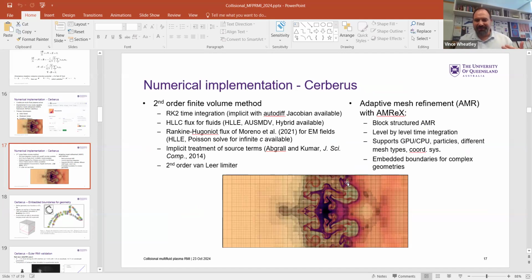So we use adaptive mesh refinement to greatly refine the cells around the solid boundary. But then we slightly unrefine them if those cells would be too small when we cut them. The reason for doing this is to make sure we're able to take a time step which is what we would expect for the finest level of the grid, instead of maybe 1,000 times smaller if we have a really small cut cell. But yes, it does come at the price of slightly coarsening some of the cells on the boundary.